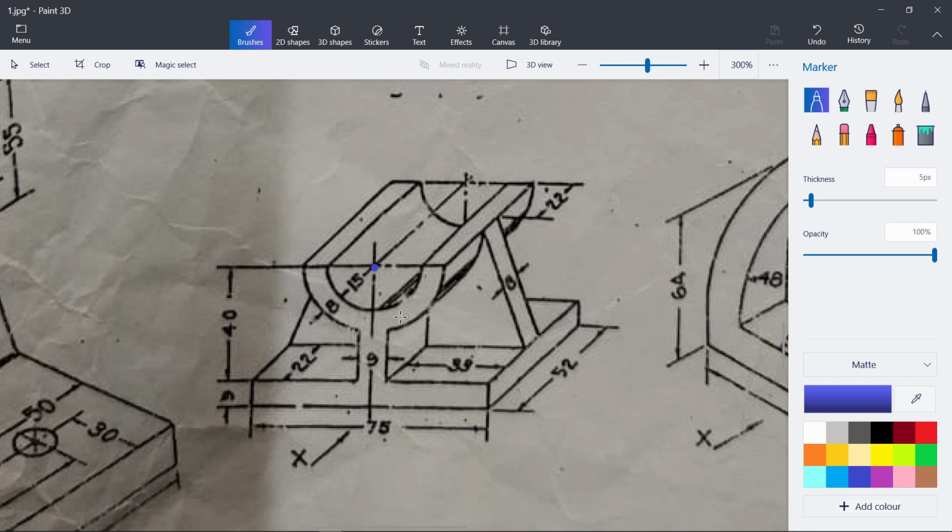So let's 3D design this particular isometric figure. Let's break down this figure into some features. First off, I can see a Y cross section feature over here on the front plane. The front plane is denoted by this X with the arrow mark. And looking at the right plane, I can see this inverted T cross sectional area.